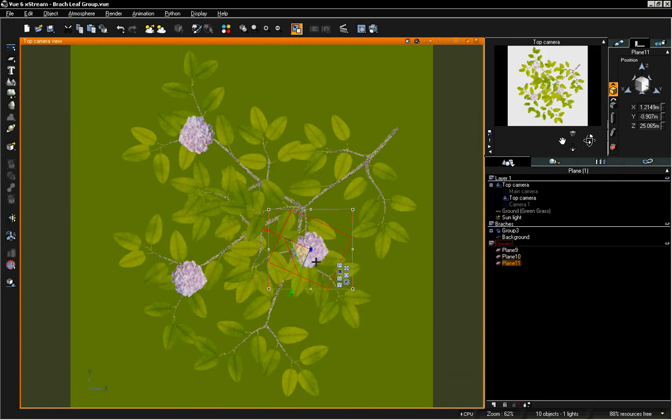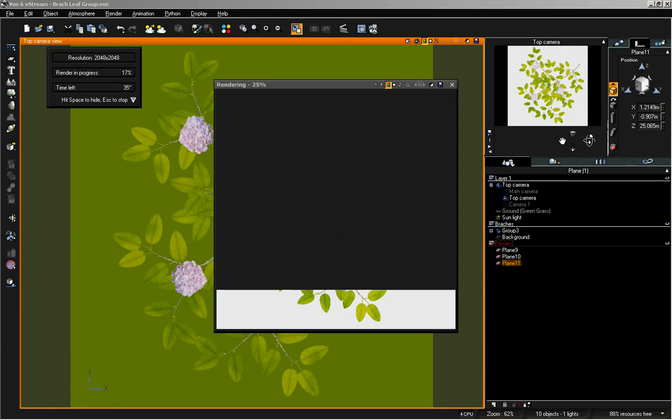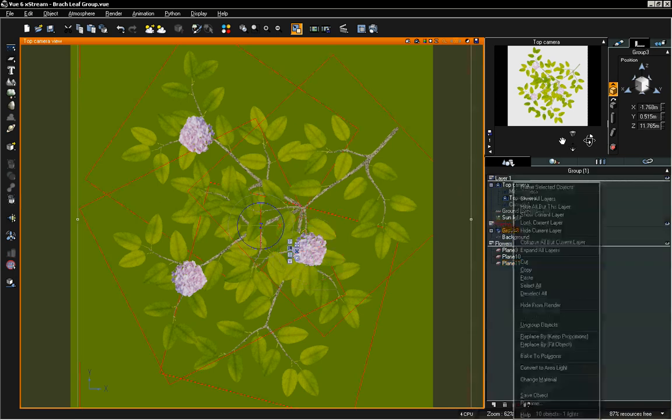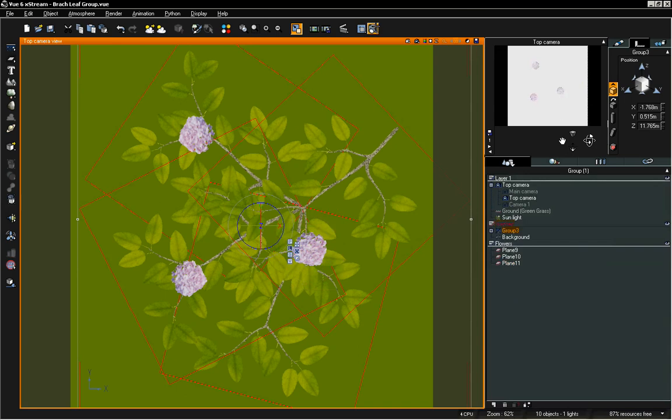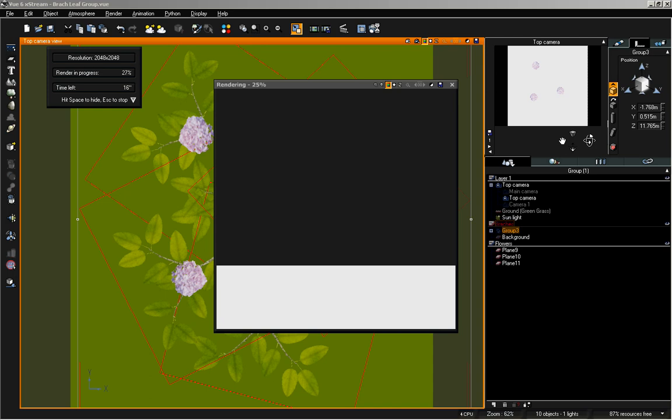And now we have a little template for flowers. So you could load in any flowers that you want, just these little group clusters, and that will add a lot more to your scenes and make them look a lot more interesting. And we'll go ahead and render out our different images for this, and then load them onto a tree and see how they look. I am also going to select our branches group and hide it from the render and just render out our flowers as their own separate group, and you'll see why once we start working on our tree.